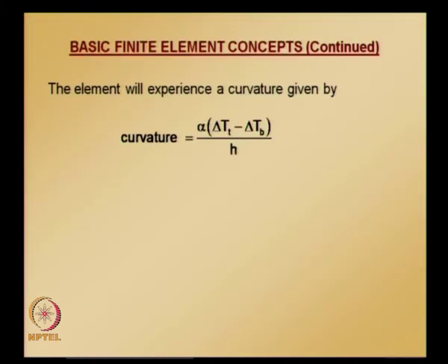The curvature which this element experiences is given by this expression, which depends on the temperature change at the top surface of the beam, the temperature change at the bottom surface of the beam, the coefficient of thermal expansion, and the depth of the beam. Here h, please do not confuse this h with the 2h earlier.